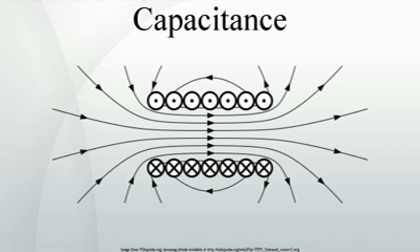In nanoscale devices such as quantum dots, the capacitor is often an isolated, or partially isolated, component within the device. The primary differences between nanoscale capacitors and macroscopic, conventional, capacitors are the number of excess electrons, charge carriers, or electrons that contribute to the device's electronic behavior, and the shape and size of metallic electrodes. In nanoscale devices, nanowires consisting of metal atoms typically do not exhibit the same conductive properties as their macroscopic, or bulk material, counterparts.